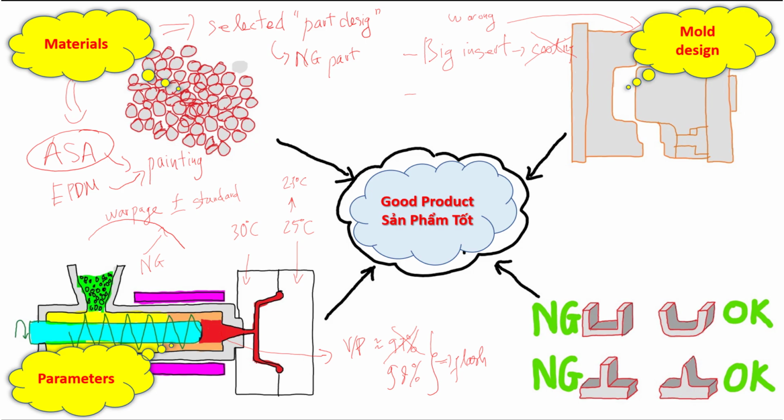And next, for example, you selected the wrong mold material. Say, unluckily, your parts have a hot spot, and with the hot spot here, you cannot use steel. Or sometimes you need to design a 3-plate mold, but actually you design only a 2-split mold, so it leads to being unable to inject.